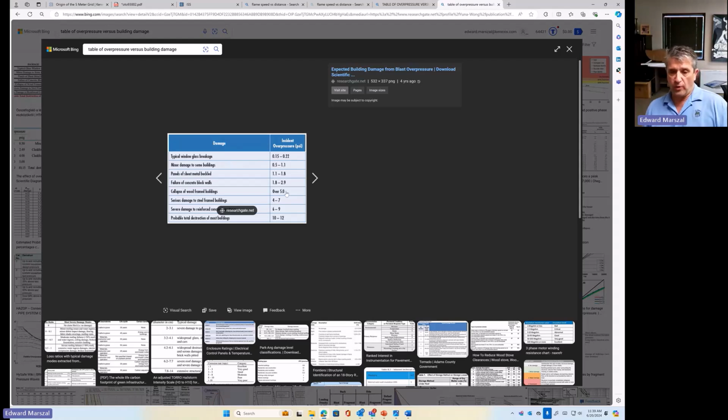Yeah, general. If you're spilling a flammable liquid above its flash point, that might be in the process, it might be a storage area. If the temperature of the material is above its flash point, that means you're going to be generating enough vapor to sustain a fire, and you're going to be creating a potential gas cloud.